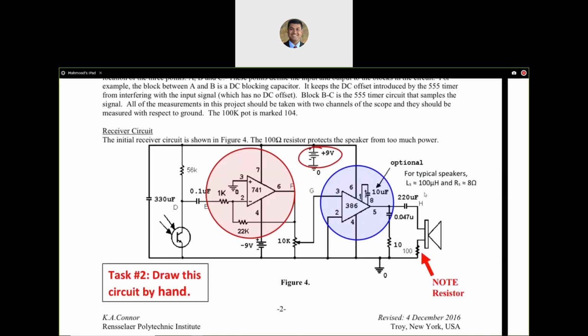I'm going to use the power rail at the top, and I'm going to connect the red wire that is coming out of this to that. And the black wire from the 9 volt battery, I'm going to connect to that rail over there, which is going to be my ground rail. So for the first power supply, you have the power rail and the ground rail that are in reference to this power supply, the plus 9. So you take the two leads of this battery, red and black, and connect them. Most people get here, but the next step is a little bit difficult.